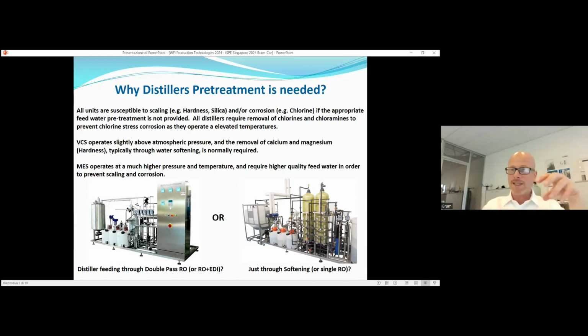The chlorine, especially its gases with the stainless steel, can create the phenomenon of pitting that is creating some pointing, some stains on the stainless steel. So the pretreatment becomes fundamental for the quality of the WFI that we obtain, and also to preserve the technology, the machine, in the medium long term.